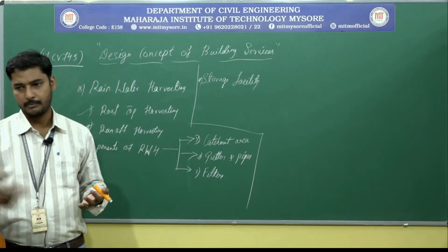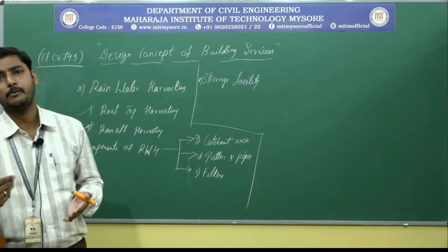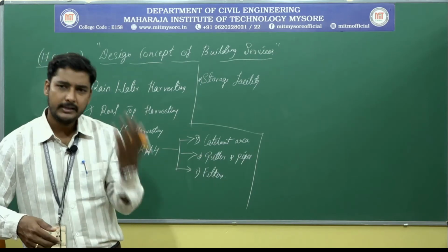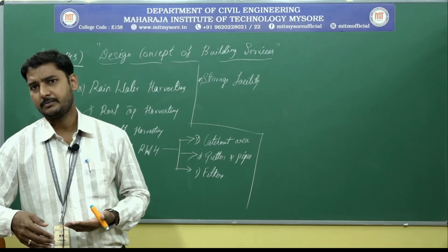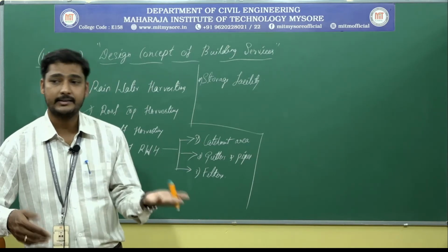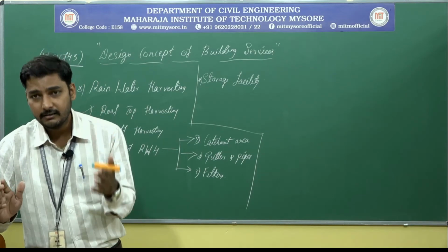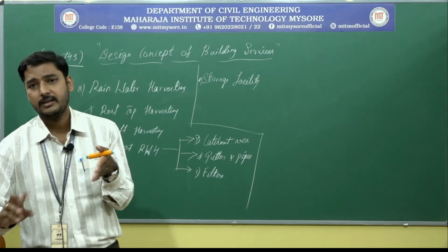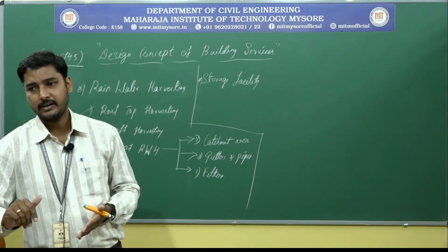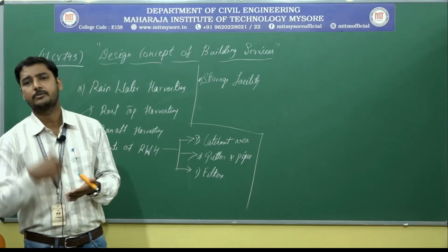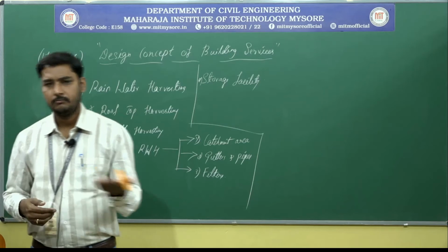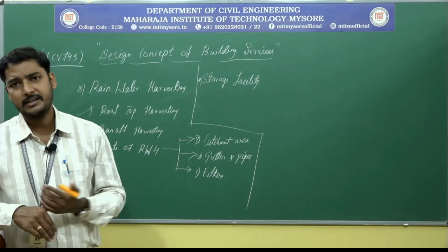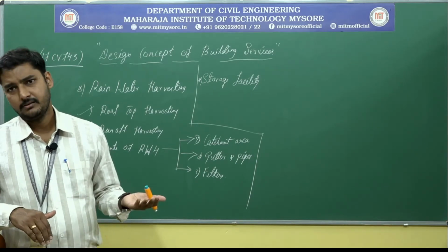Ground floor, first floor probably. In some other cases we may have 1 or 2 more members, which will lead to 10 members. Each day the requirement is around 200 liters per person, or 135 liters, or 100 liters, depending upon the comfort zone and locality. It depends on all these practical parameters. We need to consider the per day requirement, multiplied by the number of days, because the tap water may come once in 2 days, or weekly twice, or weekly thrice, depending upon the conditions and the season. We can decide the availability of water.